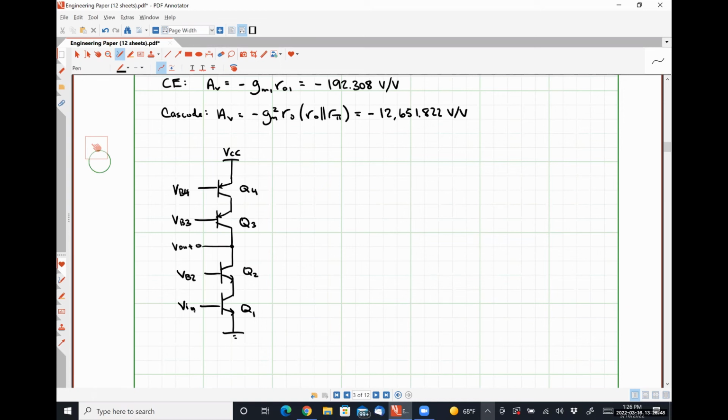That is obviously going to change our output resistance appreciably. So we should see that our gain will go down because our biasing current source no longer has an infinite small signal impedance.